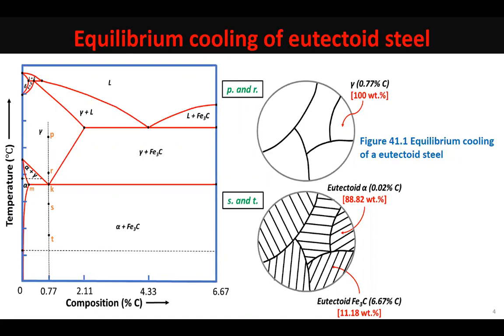And mind you, when we do heat treatment, we reheat the steel from room temperature till the steel attains a fully austenitic state or a partially austenitic state. We will never go to a temperature beyond the austenitic region. So whenever somebody asks you to elaborate on the microstructure evolution in any type of steel, the highest temperature that you need to take is when the steel is in the austenitic region.